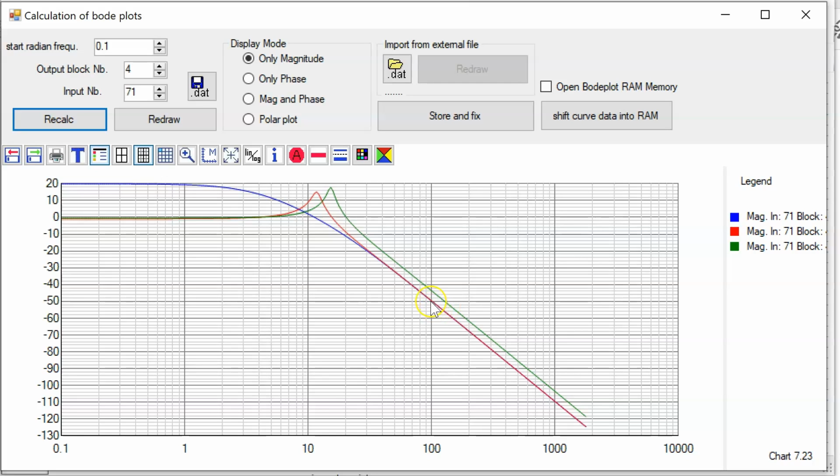No, not 20 dB, factor 2 is 6 dB, this is 6 dB higher, not 20 dB. Independent of this, it looks like a system where the resonant peak is a little bit higher, so the damping is a little bit smaller. But what we cannot see in the Bode plot is that now we have an unstable loop.